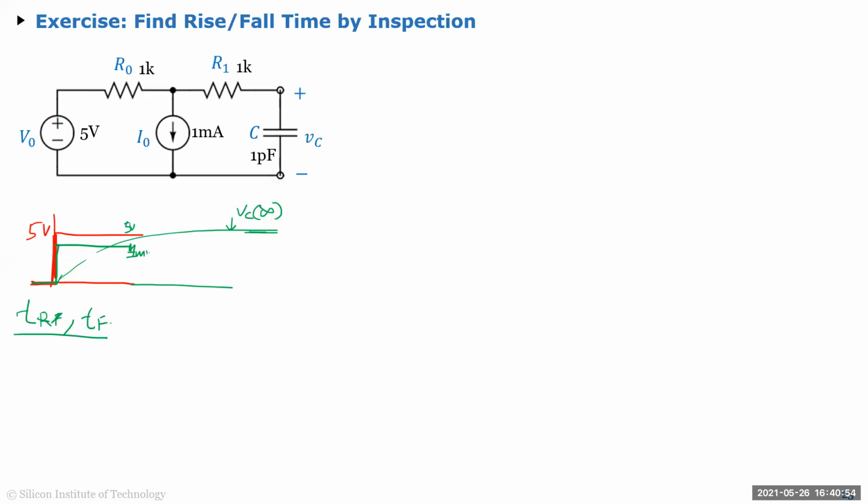Okay, perfect. Yeah, that's good. While others are solving, I think this got it right. So what Sandharani said is perfectly fine too. If I'm asking you for the time constant, then that's what's called the open circuit time constant. You take your capacitor and make all your voltage sources zero and current sources zero. So the voltage sources become short, current sources become open.